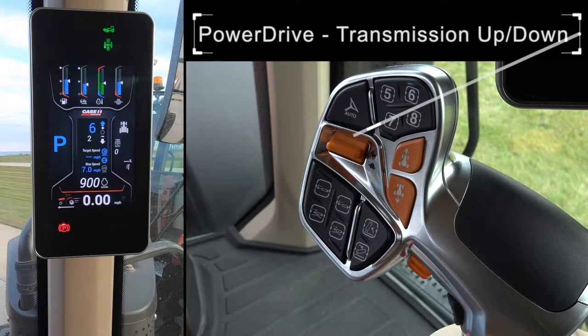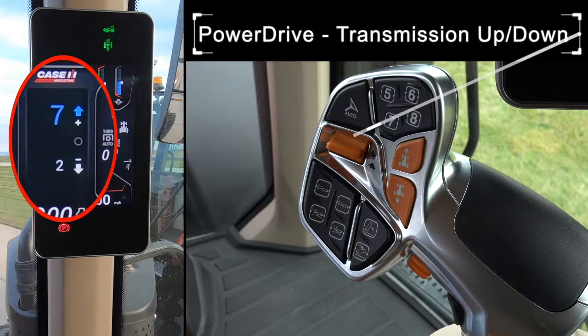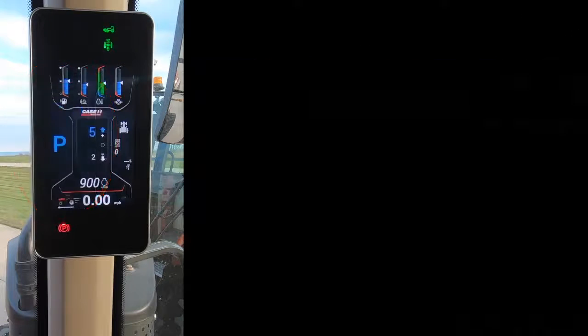Power drive. Pushing this button up and releasing it will shift the transmission up 1 gear. Pushing this button up and holding it will continue shifting the gears up until it's released. Pushing the button down and releasing it will shift the transmission down 1 gear. Pushing the button down and holding it will continue to shift the transmission down until it's released.